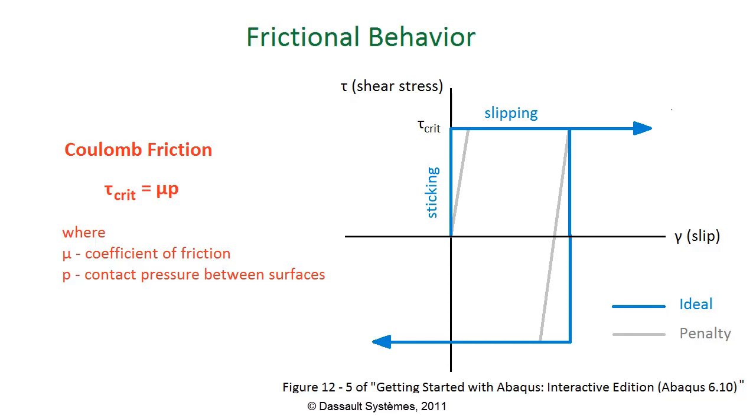The static kinetic exponential decay allows the user to specify static and kinetic friction coefficients. In this friction model, the static friction coefficient decays exponentially to the kinetic value. Test data can also be entered to fit the exponential model. In addition, you have the option to specify elastic slip.